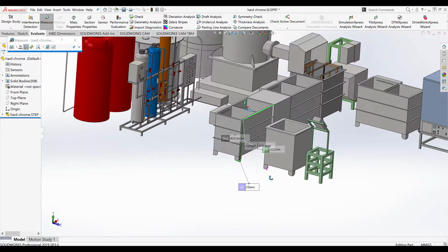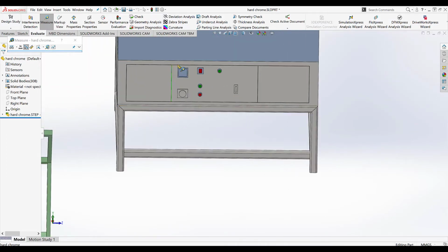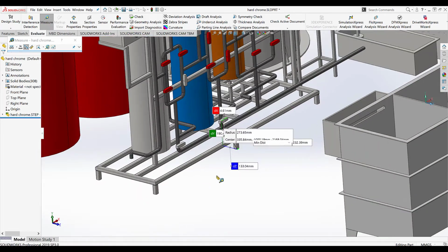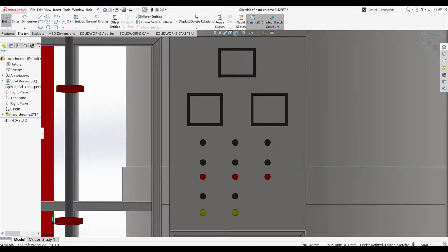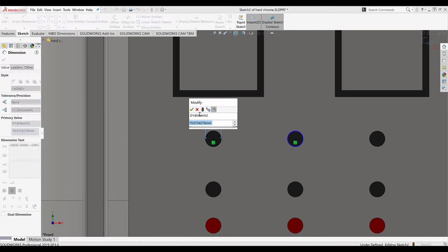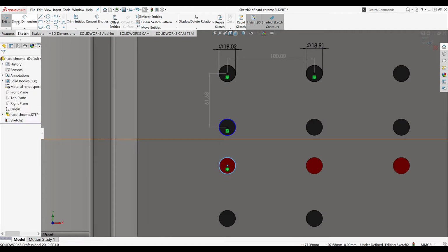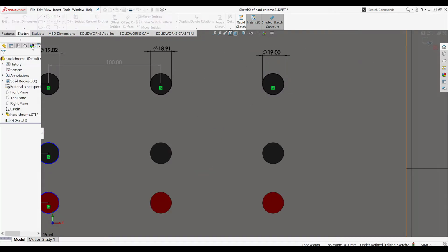One of the first steps I like to do is open up the STEP file in SolidWorks. This is where I would typically identify the human machine interfaces and gather the key dimensions of them, such as the height of the control panel or the height of the manually operated valve. An advantage of using SolidWorks is I also have the ability to use a sketch tool, meaning that I am able to gather measurements which might be more difficult to achieve using the measure tool. They are also all laid out on the screen like you can see here, rather than needing to note it down manually.